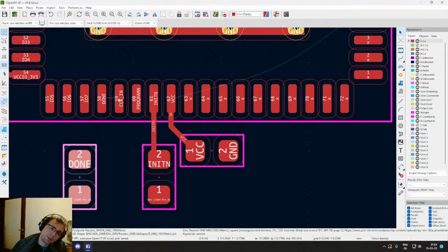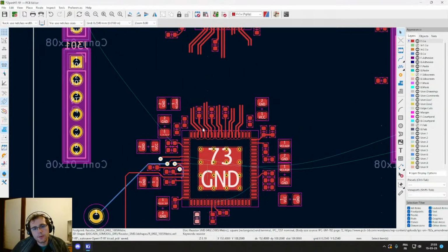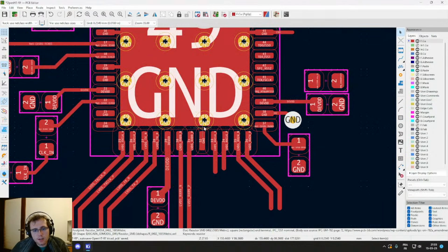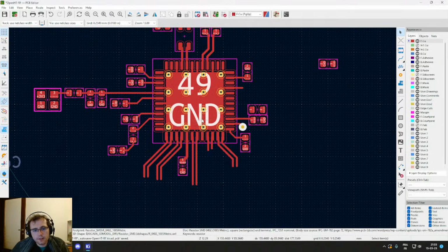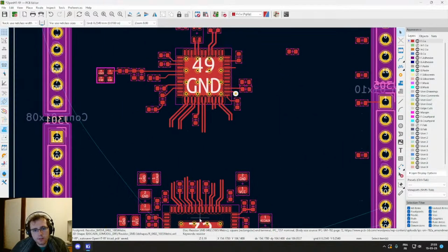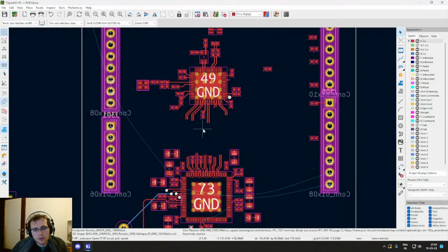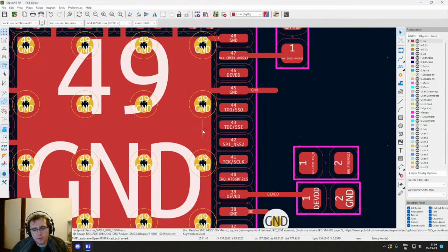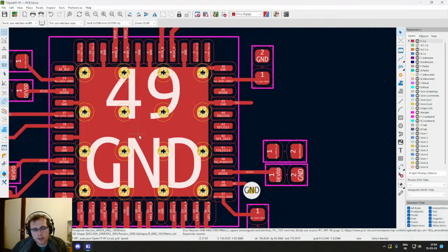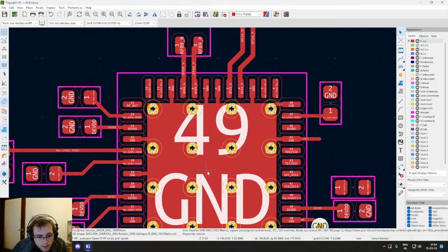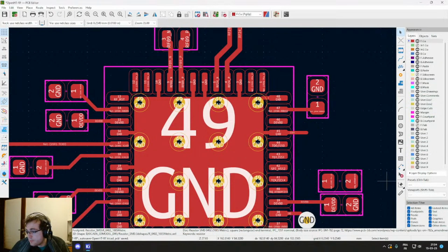So clock input. This clock input is generated by the transceiver for the FPGA, and it's 26 megahertz supposedly. It needs to be carefully routed too, but it's the opposite of the transceiver. Maybe we should route that first. Yeah, so it should take priority with regard to the other I/O signals.